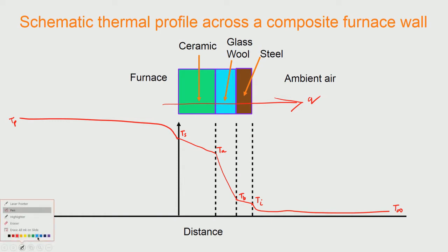So, you can see that the heat is going down this because of the gradient, down this because of the gradient, down here because of the gradient, down here and down here into the air. Okay. So, this is how the heat flow is happening, and if it is steady state, then the slopes have to be adjusted according to the thermal conductivities for the respective shells.